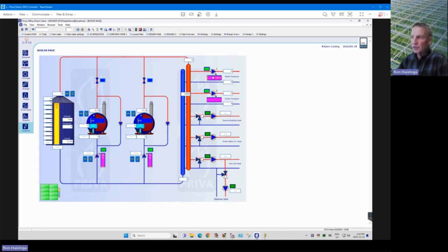So when the greenhouse needs heat, and if the boilers are not supplying the heat, then the heat will come directly out of the tank. The return from the greenhouse will be going into the blue line here and coming to the bottom of the tank. So the water temperature of the tank is basically determined by the return water of the greenhouse. So to go through some settings.